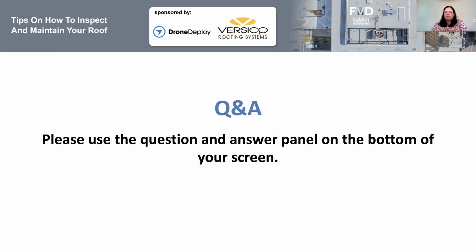Great. Chris, another question for you is, what are the most common types of issues with a standing seam metal roof system? Standing seam, generally the fasteners, a lot of the more premium type systems have clip systems where there's no exposed fasteners. On a lot of the older buildings, and more industrial type, we see that there's a lot of fasteners, and they have those EPDM type or neoprene gaskets on those fasteners. Those do wear out. They have a shelf life, so to speak. And that's where we commonly see leaks. Also, if there's been a lot of traffic where deflection has been created from somebody stepping in the wrong areas, it starts to crease and crack, and you'll see those start to rust and fail over time.